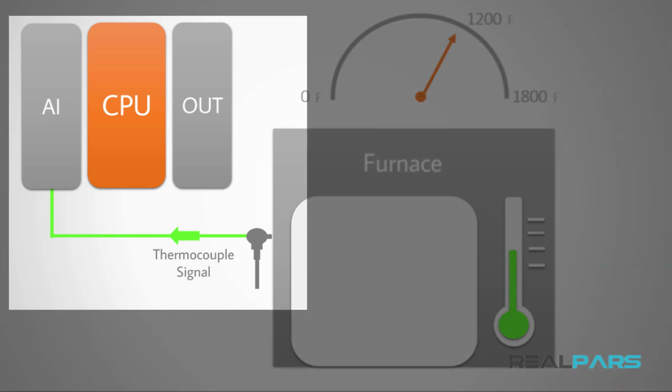In fact, in industry, due to the fact that the receiving signals from a thermocouple could be very vulnerable to the noise that is generally present in an industrial ambiance, and the calibration of the thermocouples and wiring them to the analog input modules has its own problems, usually they convert the thermocouple signal to a 4 to 20 milliamps standard signal, which is also an analog signal, by means of a signal converter, and then they connect it to an analog input module.